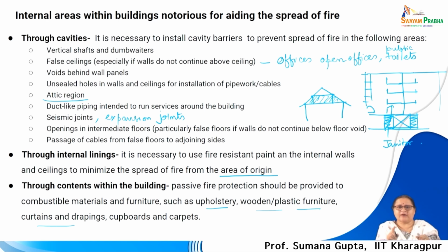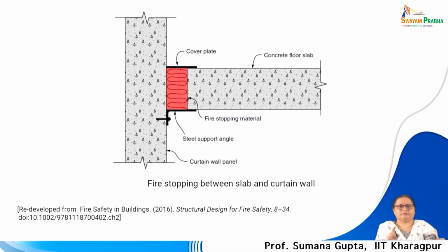So, all these are vulnerable and are to be kept in mind, like their fire rating are to be looked into before they are inserted in places where there can be a chance of fire. Say a residence, there may be a kitchen where there is fire. So, the appropriate wall lining material, appropriate flooring material should be there, appropriate furniture should be there, to avoid any case of fire, and if it happens, the fire spread should be under control.